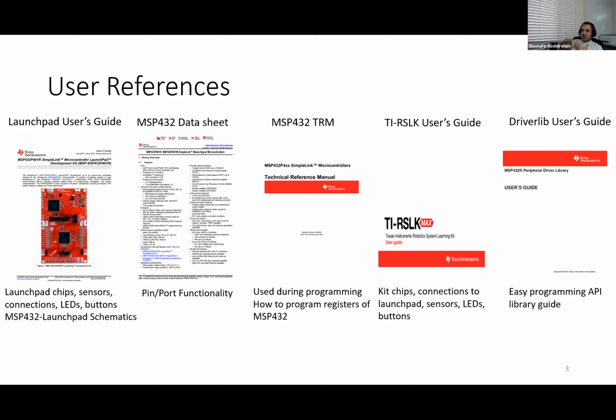It is basically the API. So when you program an embedded system like this, you are going to need something more than what C or C++ can give you. For example, if we want to program some registers, each register inside this micro has a keyword that we can use, so that the compiler knows we want to program this specific register.